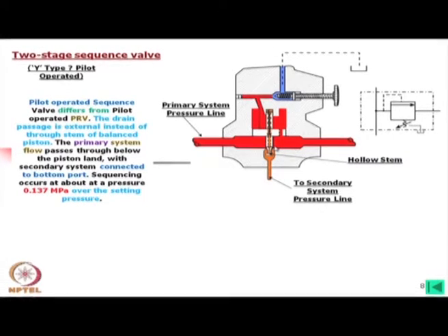Ordinarily, when there is no flow, it is completely balanced, with no force acting except the spring force, which just allows it to sit on this position. So the seat will not leak, and with a small force it will remain closed.